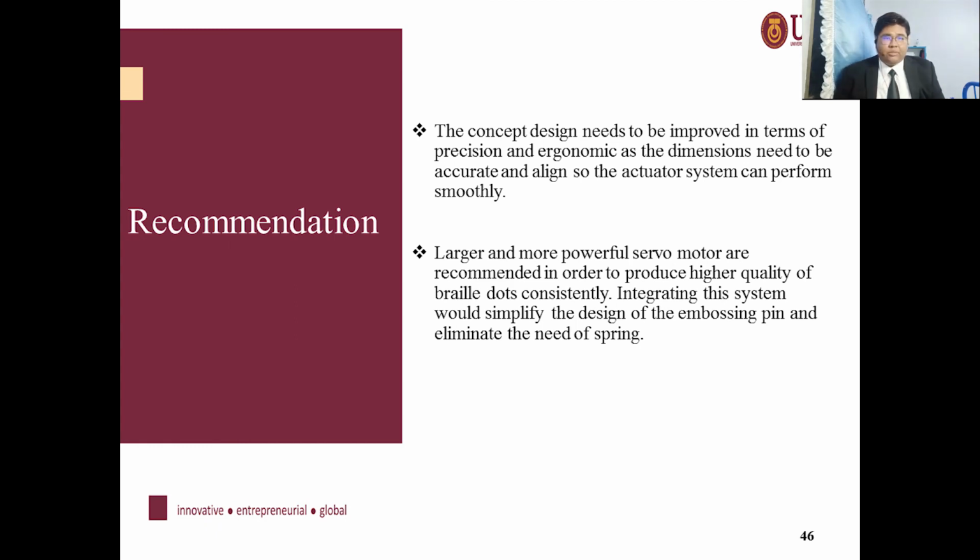So the recommendation for this project is the concept design needs to be improved in terms of precision and ergonomics so that the system can run smoothly. The second one is the servo motor, which needs to be larger and more powerful, but it also makes the actuator system larger and more expensive due to high power and size. But integrating the system would simplify the design of the embossing pin and eliminate the need for a spring.